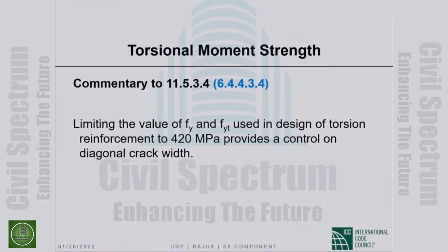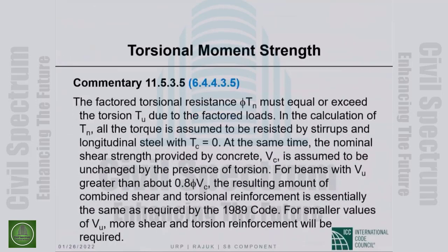This is commentary: limiting the value of f sub y and f sub yt used in design of torsional reinforcement provides a control on diagonal crack width. I told you that already.